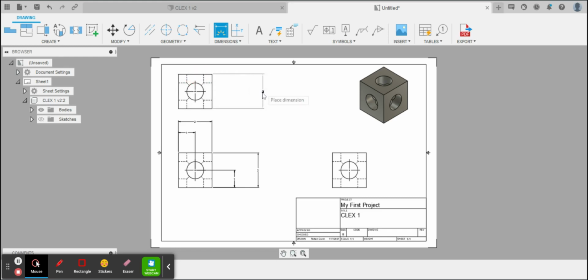And I'm going to put on the right hand side, give me 2 inches. And now I'm also going to do it from the bottom line to the center mark. That gives me 1. Okay, and those dimensions are done. It looks good. Now notice we have a three-dimensional object, a 3D object, so we've got 3 sets of dimensions. 1 in the Y direction, a second set in the X direction, and a third set in what's called the Z direction, or going into the page.